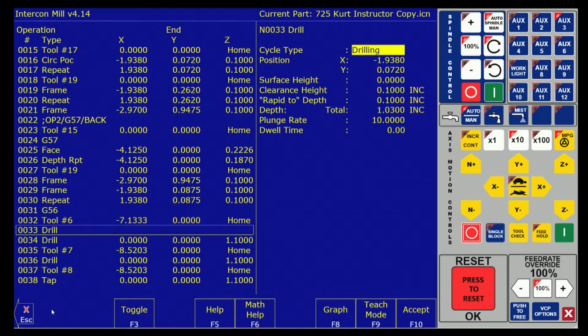Drilling goes straight to depth, no pause and no nothing. Deep hole, the tool's going to drill as far as you program it, then a full retraction to pull chips out. Drill another depth, full retraction, which is what you guys were using that had coolant. I recommend you keep using that if you have coolant. Chip break is when it's just going to pause.